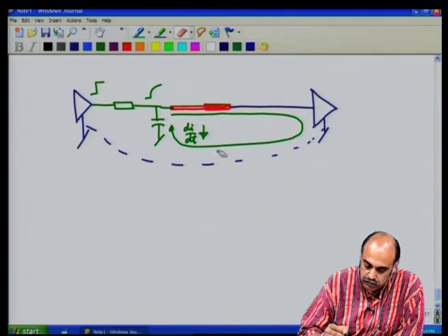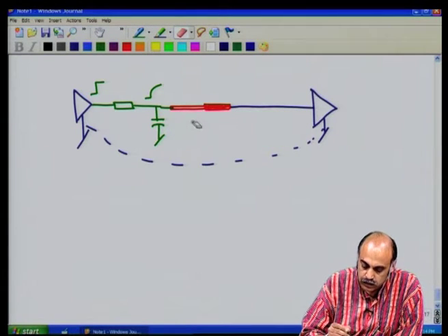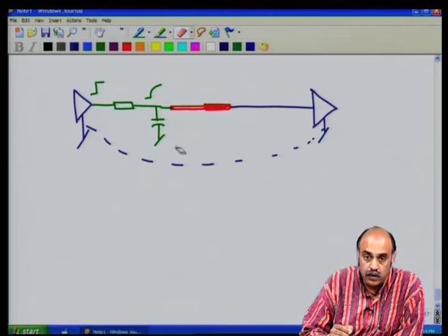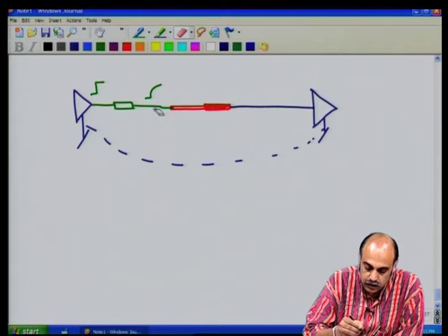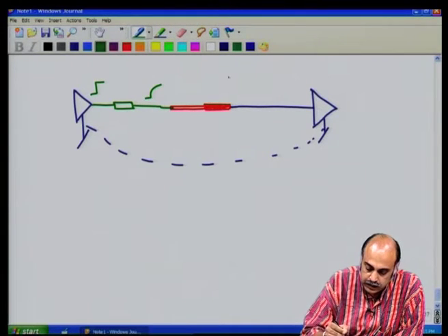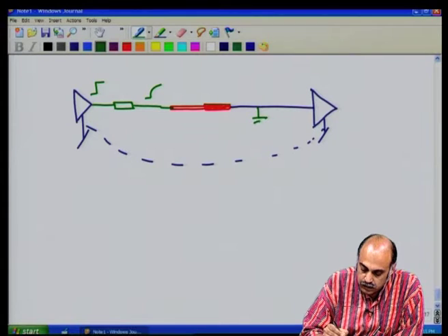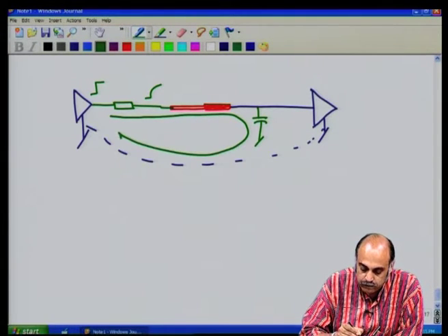However, keep in mind that you can do it this way, and when you are going about it, be careful, do not put the capacitor on this side, because if you put the capacitor on this side, then you are still having a pretty high loop area.